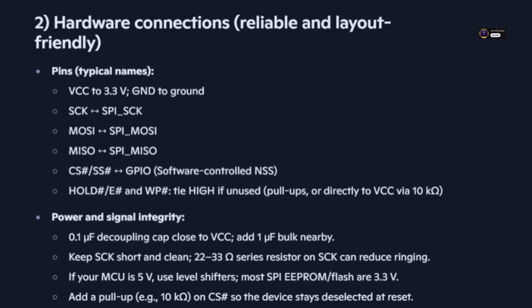Now, some important reliability tips here. Any unused pins on the flash chip, like HOLD# or WP#, write protect, usually need to be tied high, often through a resistor, to your voltage supply so they don't float. Power needs to be clean. Always put a small decoupling capacitor, maybe 0.1 microfarad, right next to the chip's power pin, plus maybe a larger one, like 1 microfarad nearby for bulk capacitance.